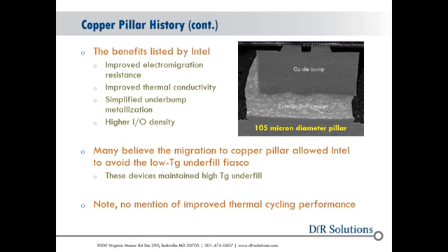If I take a silicon die which expands by 2 parts per million and I attach it to an epoxy substrate which expands by 14, and it's a relatively rigid attach, right? Typically, we think about application environments where there's lots of power on and off, and we're seeing, as we go to lower process nodes, the die get hotter. It's going to be a real problem.